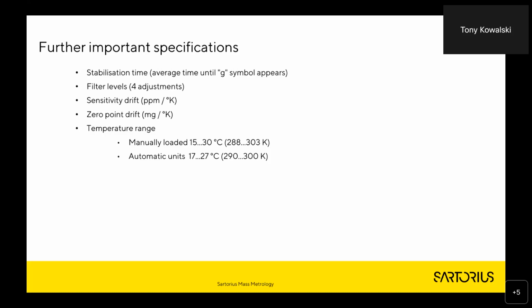It may just change by 1 or 2 digits in that 5 seconds as the air is still moving in the weighing chamber. So stabilization time is always given. You should reach that. If you don't, then there may be some vibration or other disturbance in the lab. Nice is to see the stability indication and wait maybe 5 seconds, then take the value.